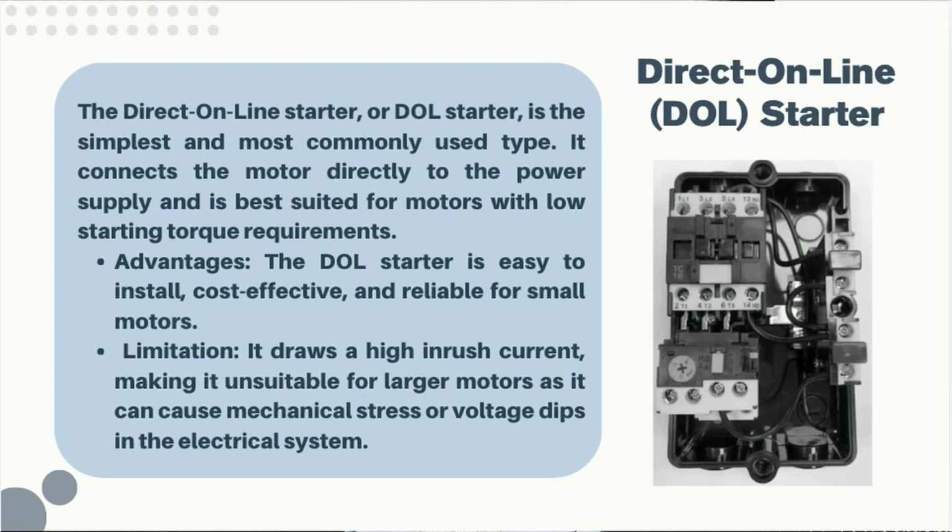Advantages: the DOL starter is easy to install, cost effective and reliable for small motors. Limitation: it draws a high inrush current, making it unsuitable for larger motors as it can cause mechanical stress or voltage dips in the electrical system.